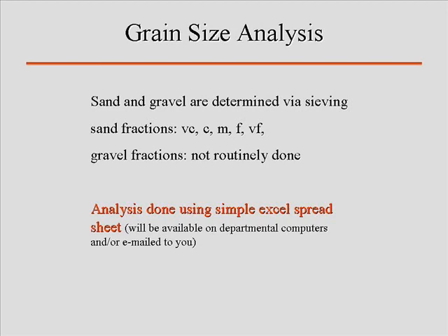You have to extract all the sediment out of the columns, dry it, and this you can put in an oven that's fairly hot. The sand will dry, and then you put it through a stack of sieves, which is what I really hate. Because again, you have to follow statistical methods for this. 15 minutes of sieving is required for each sample.